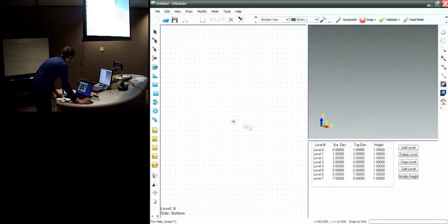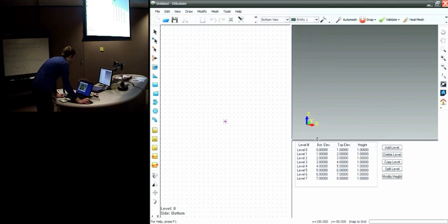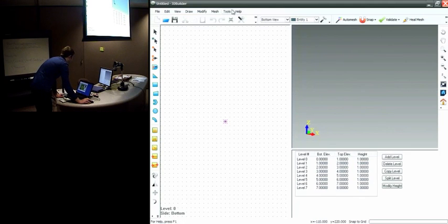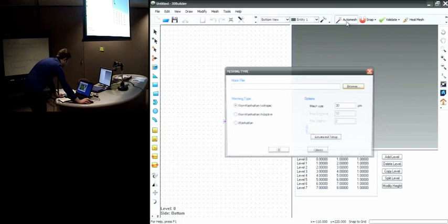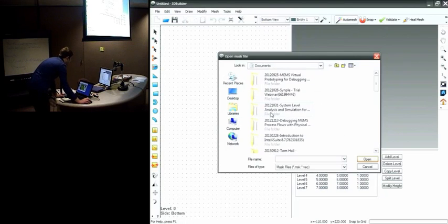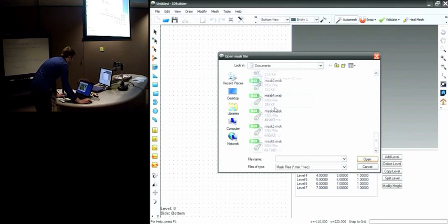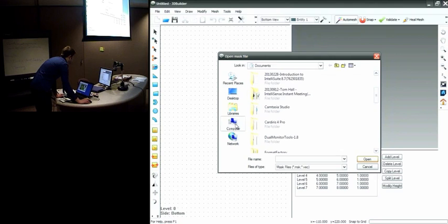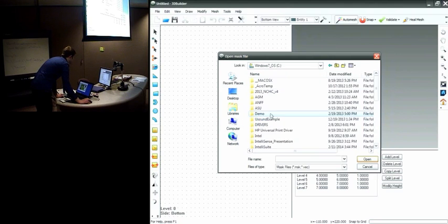As I mentioned before, on the left it will show your 2D layout and all of your layer information down here, and then on the right it will have your 3D model. So first, to create this 3D model, we're going to use this Auto Mesh tool just to import that mask from before. If we already had the 3D model generated, that would work as well.